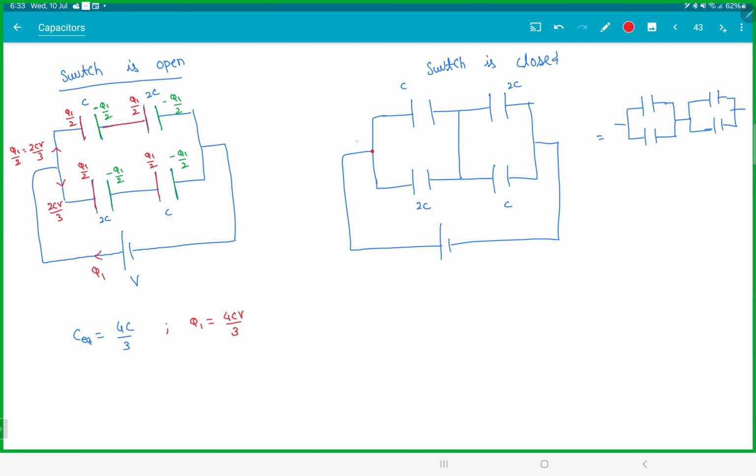Meaning if you take this point as A, this entire line is the same actually. Let's call it B. Let's call this point C. If you look at this, the potential difference is VA minus VB. This is VA minus VB. They both are in parallel. The entire center line, you can just compress into a single point. Is this making sense? This is what I was saying.